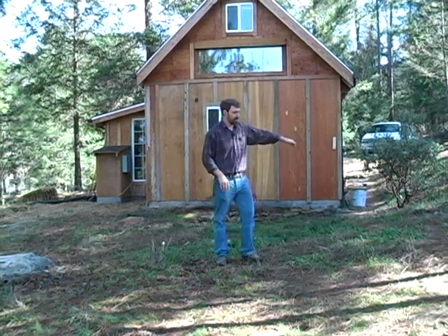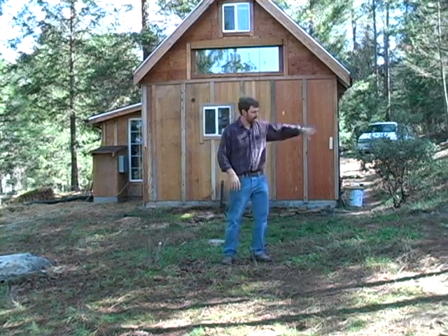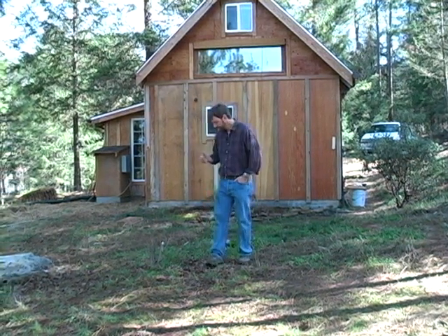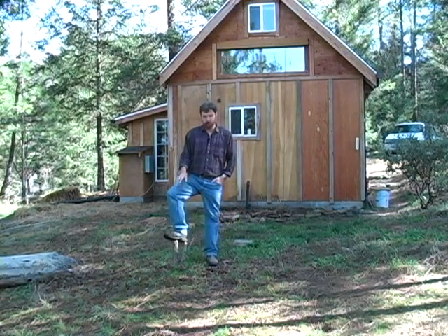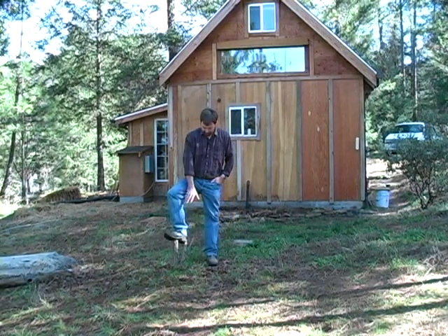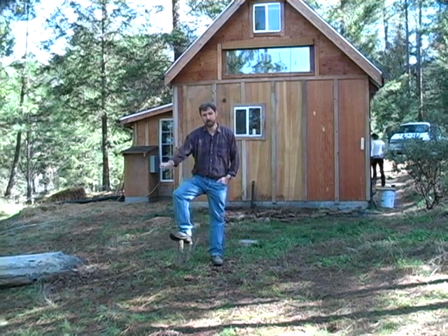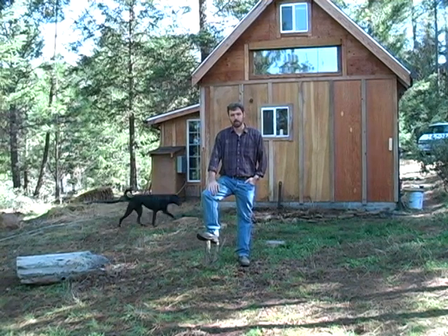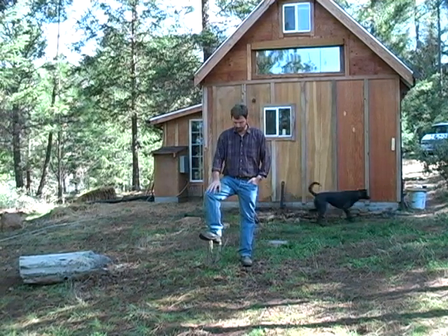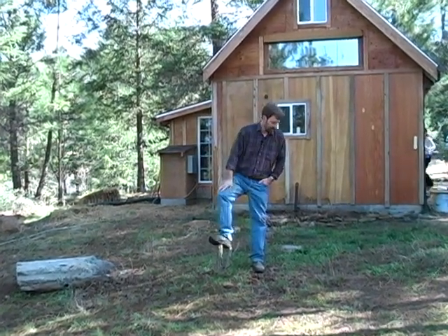So on this side where we have a fairly significant cut, we'll want to slope that back, make sure we're either draining around the slab or placing some type of curtain drain in that area to handle any water that may come down. Other items that you want to look out for are trees. In this case we had a small oak tree here that we've cut out. I left it about a foot tall so I can wrap a chain and pull it out so that I get the root structure out. You can't have any roots or organic material below your slab, so you want to make sure that you pull that out ahead of time.